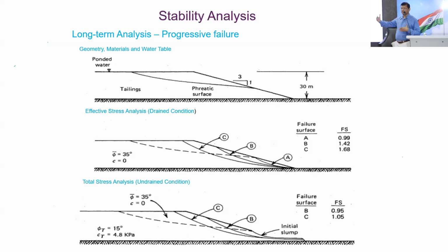There are so many other factors also, not only stability, because for stability you can be steeper than a 3-to-1 slope, but mainly for erosion and other activities, we prefer a slope flatter than 3-to-1. In some cases we can also go to a 4-to-1 slope at the end.